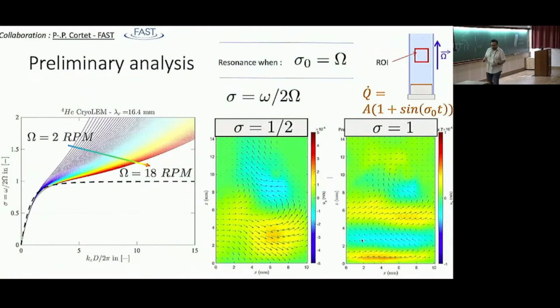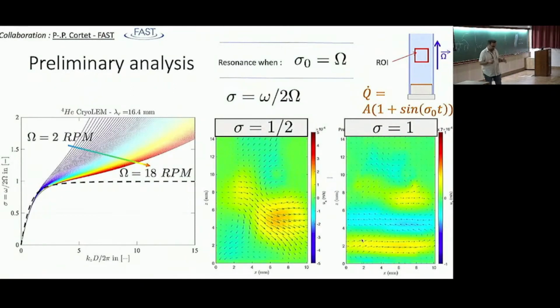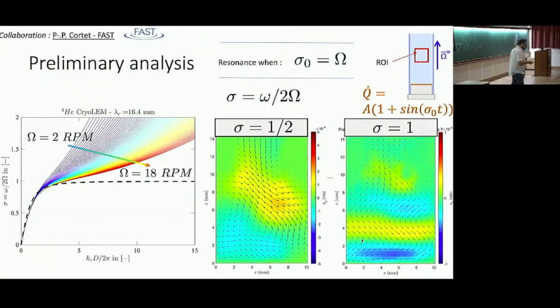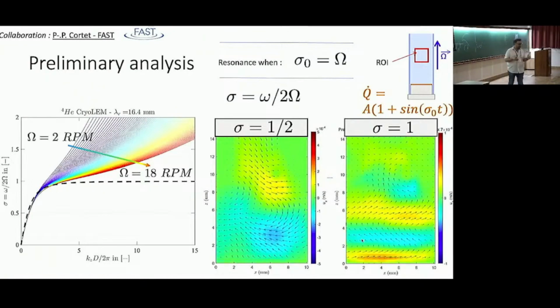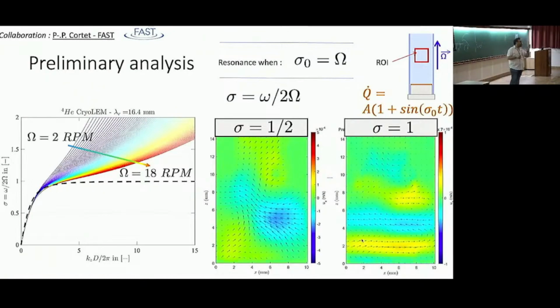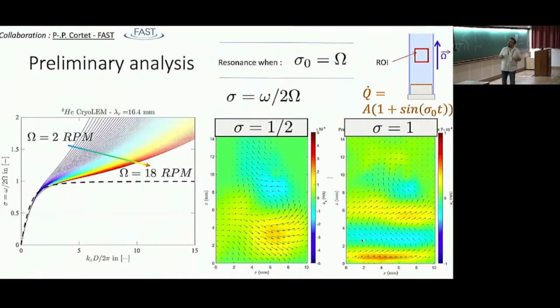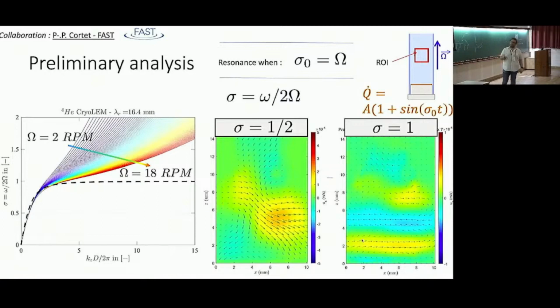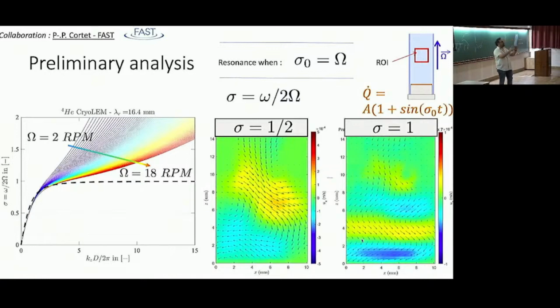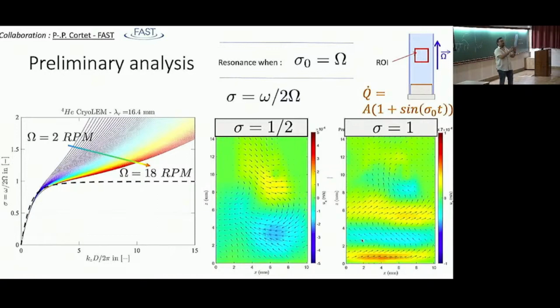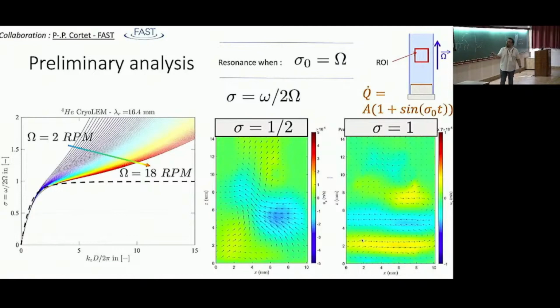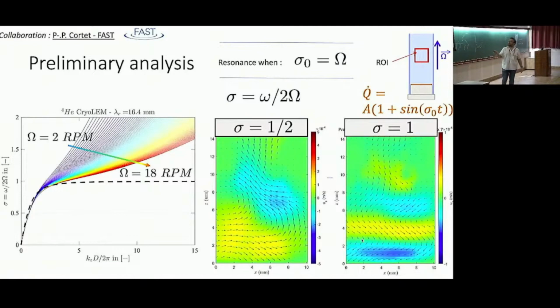So to do that, we've been trying many things. Tracking is not too bad. Maybe we'll come back to it with a full tracking of lines, etc., but it's hard technically, so we didn't manage so far to reach this level. So we use PIV, with a relatively big window, so that we get those velocity fields.